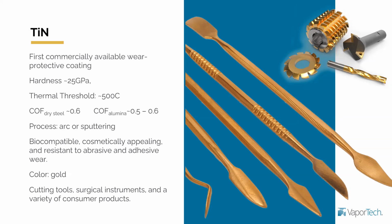Again, this can be done with cathodic arc or can be done with sputtering. It's a biocompatible material as well. Cosmetic appealing, very hard, resistant to abrasion and adhesive wear. Has this very typical color, gold. It can vary a little bit paler, a little bit darker, depending on the amount of nitrogen that you have in the coating. And here's some of the applications, which I'm going to summarize at the end with a table moving forward.